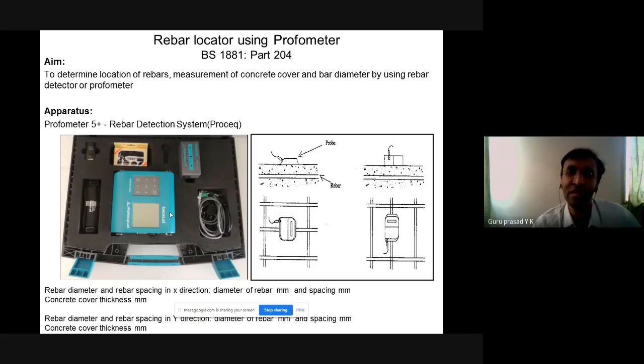They'll say we'll provide larger spacing of reinforcement, so lesser steel will be used. They'll say nothing will happen, don't worry about it. In such cases, when there is distress in the structure, like in slabs, you suddenly start having deflection and it starts to sag. In that case, what I've seen practically when I've gone for checking is you don't know what reinforcement has been provided, what is the spacing.